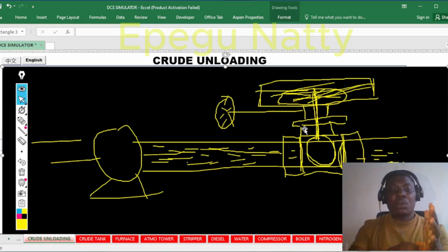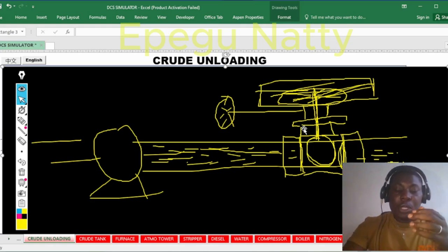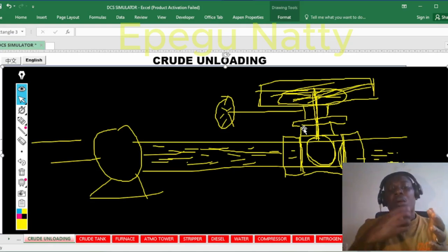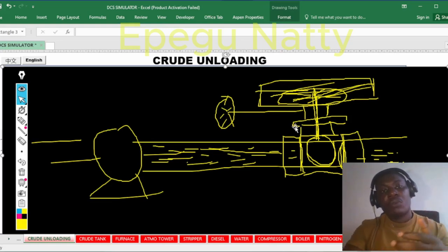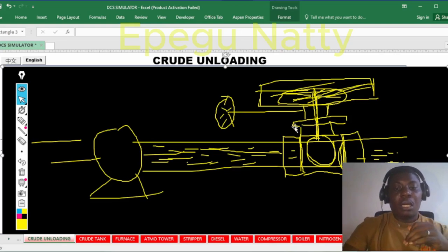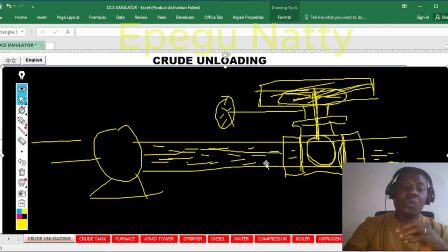Okay, and with that, it's going to cause wearing. All right. Also, what can occur here is overheating. Like we said, while the pump impellers are running, since nothing is going out and we have recirculation inside, there's going to be a buildup of temperature, and overheating is going to take place. I'm going to have also vibration inside the pump, so we don't need that. Okay, so it's very important you understand the opening of this one. So let's close this.